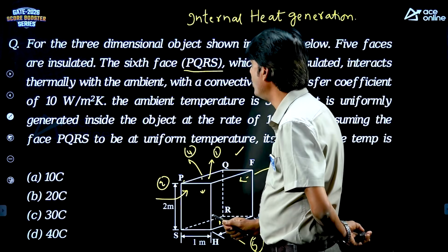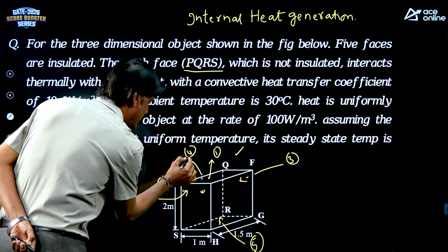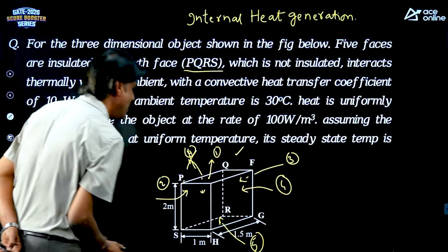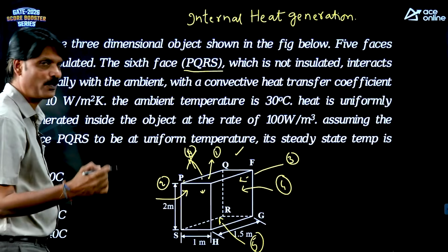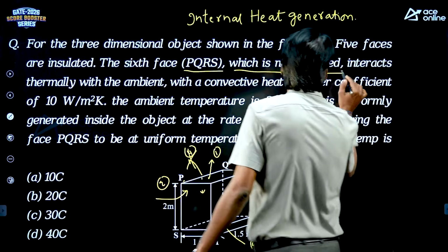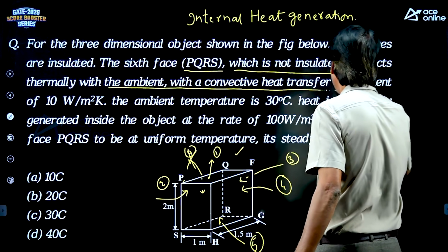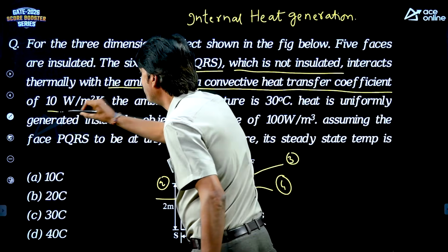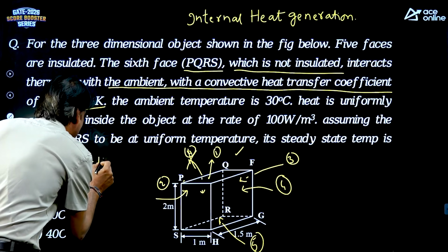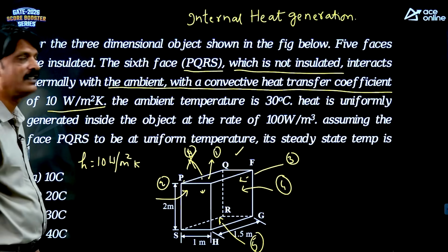So, I will take this as the 4th. This particular surface is not insulated and interacts thermally with the ambient with a convective heat transfer coefficient h of 10 watt per meter square Kelvin.